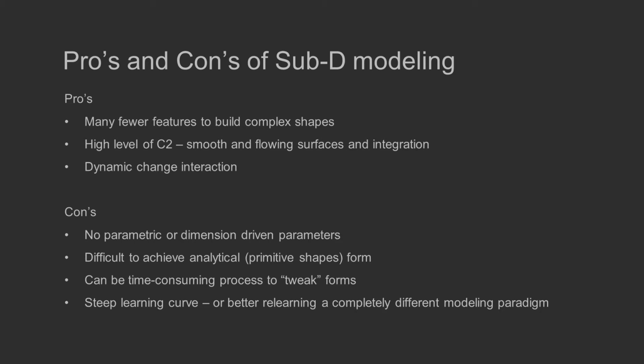Once you go in and you define or redefine the Sub-D and leave that feature to update it into NURBS, which is compatible with the rest of the solid modeler, you can't go back and undo the work that you've done. You're basically, your session is done as far as undo.